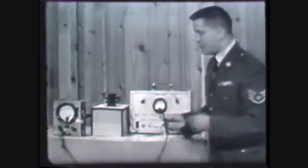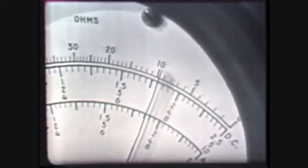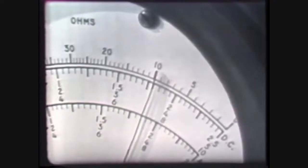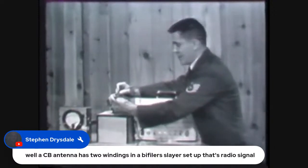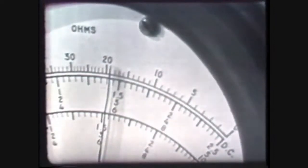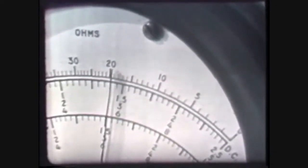So let's go ahead now and measure the resistance of the primary winding. All right, if we'll take a look at the meter now, we'll see that the primary winding has about 10 ohms of resistance. All right, let's go on over to the secondary winding and see how much resistance it has. Remember now, we're on the ohms times 1 scale. And this time we can see the PSM6 indicates about 20 ohms of resistance for the secondary.